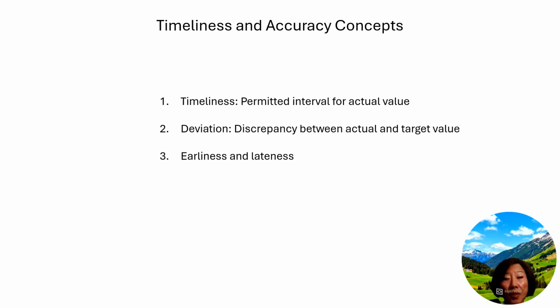5G systems implement sophisticated packet scheduling algorithms that handle mixed traffic with different timeliness requirements. This might involve techniques like earliest deadline first, EDF, scheduling, adapted for the wireless environment, or multi-level priority queuing with preemption for critical traffic.